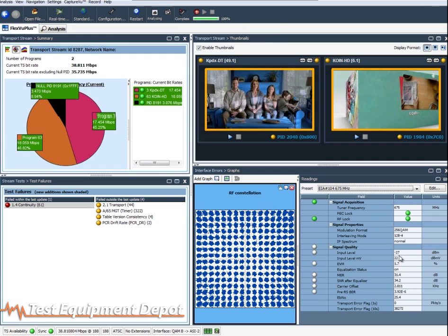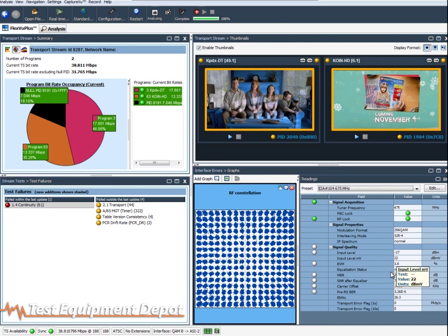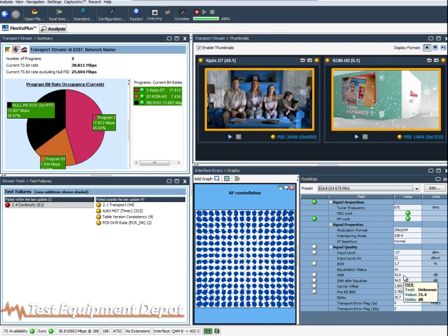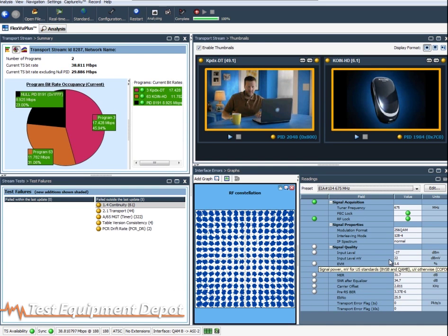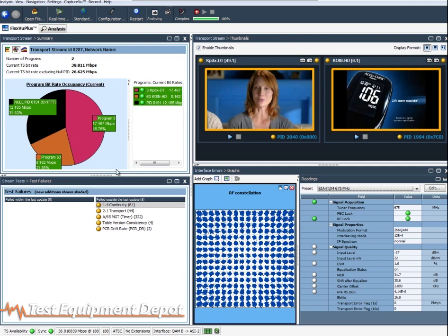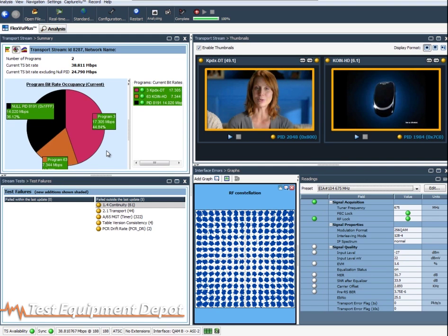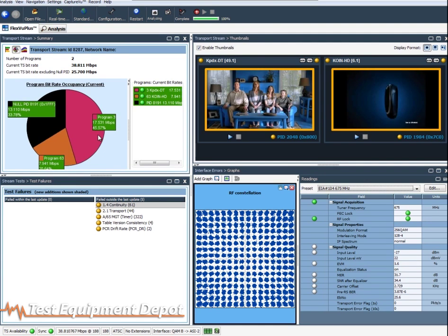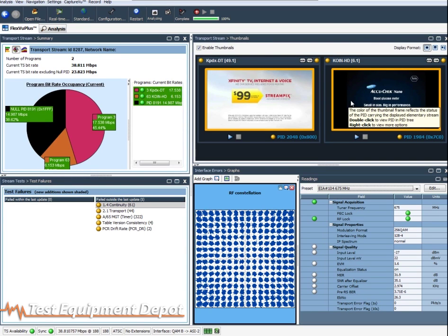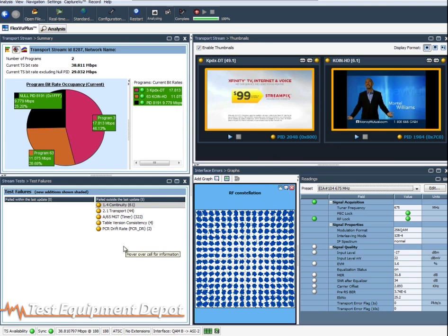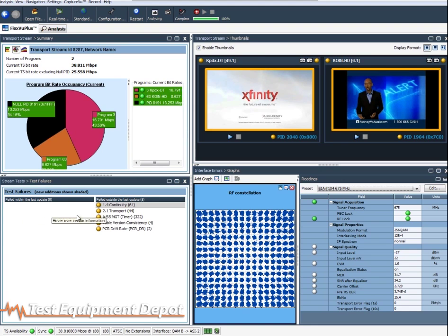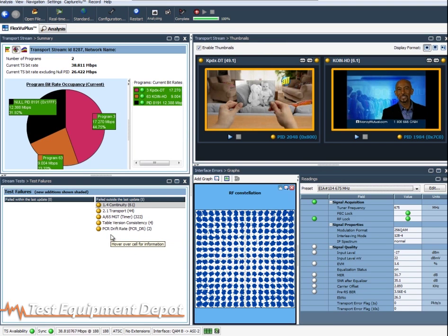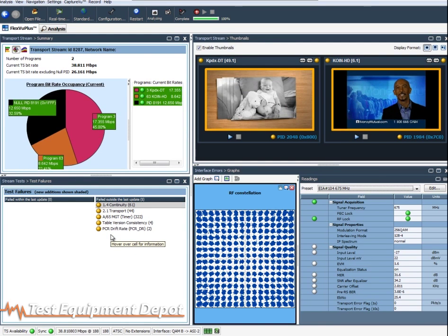We also have our RF measurements here, the signal power level, and then the modulation error ratio, which is like a signal to noise measurement. So we have all of our measurements here. Then the demodulated signal we feed over the ASI jumper, and then the MTS4000 analyzer takes care of looking at all of the program parametrics as well as showing us thumbnails of the information that we're looking at. The lower left-hand corner provides us measurement display, red being the most recent errors, and then the yellow amber ones are errors that have since then gone away and are kept in memory.